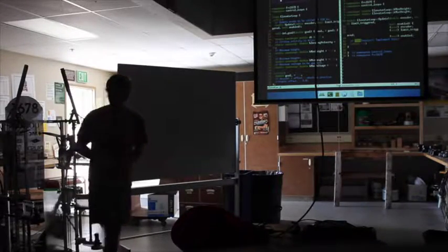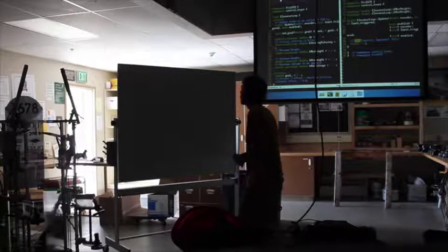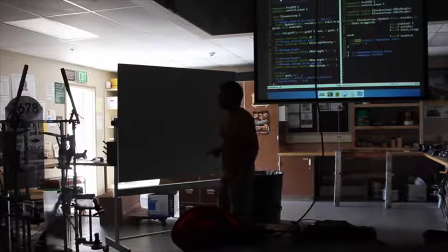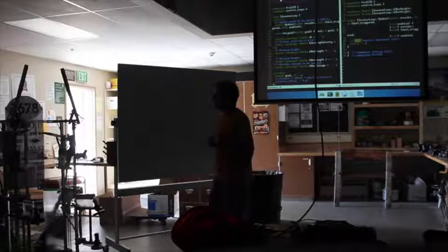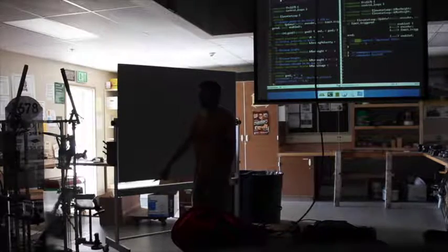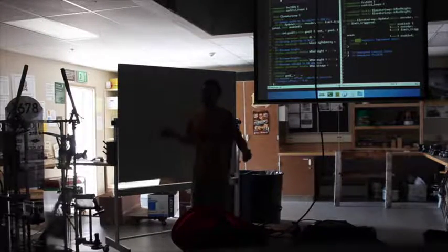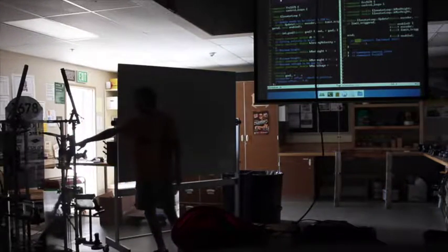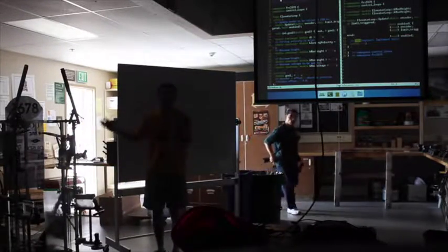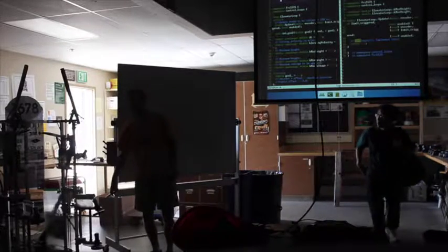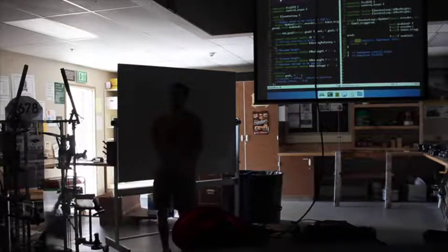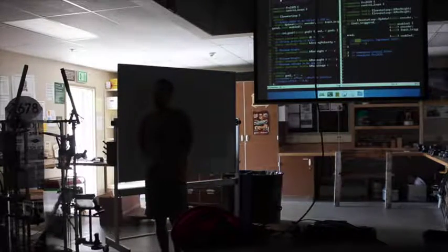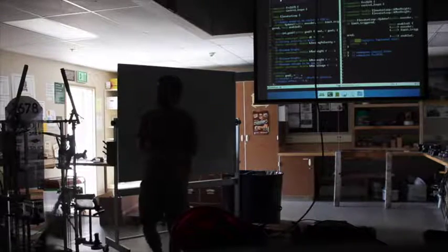So do we need to have a limit in there such that if it travels X distance, we know that it started below the Hall effect sensor, and we don't want it to overrun the bottom? I like to solve that mechanically, but you put the limit at the bottom rather than in the middle. But we can make this more complicated, but I think we should just ignore that and require the user to start it above. And then I would say in a competition robot, I'd recommend putting maybe a second one down at the bottom, so you know if you went too low and didn't find it. Or you could have a timeout if you wanted, where you've gone X and you didn't see it, that means something.